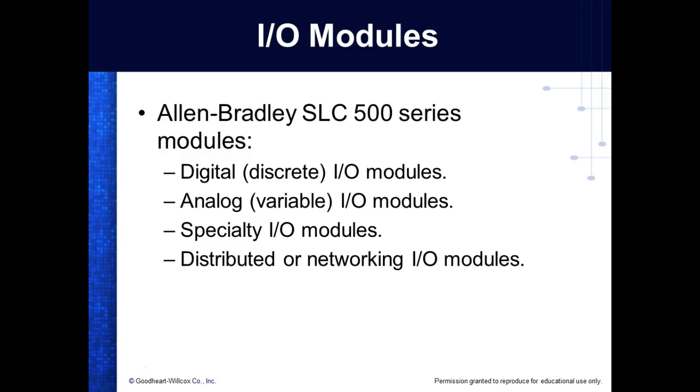Analog. I could buy an analog module. We didn't have them. The 1100 has analog inputs on it. The 1200 that we have, the 1214C, has analog inputs. It's got 2 analog inputs on it. And then we bought an analog output for that.